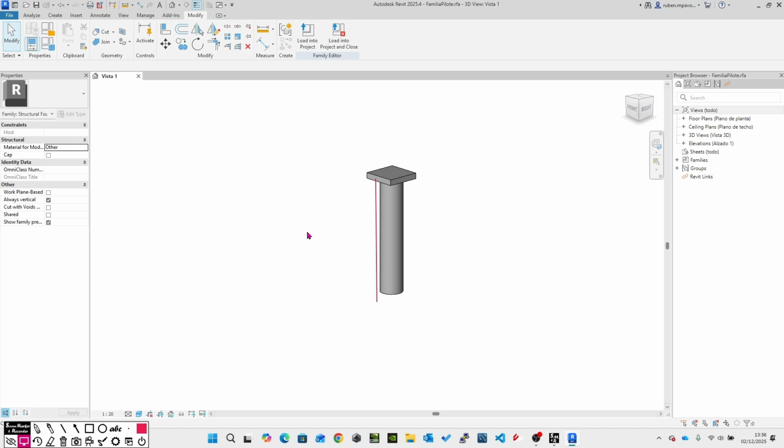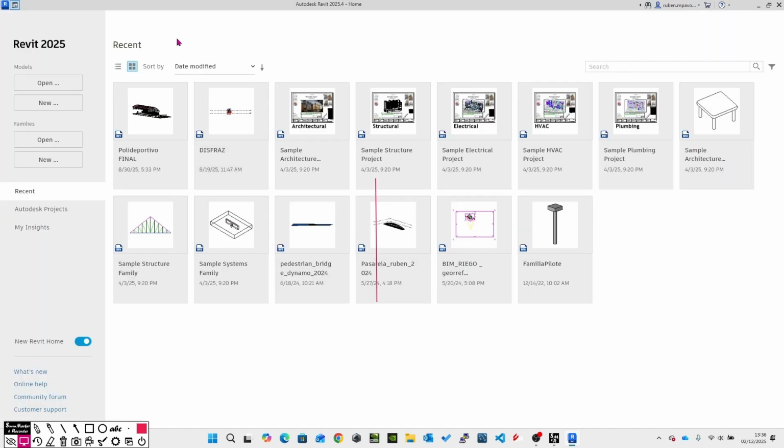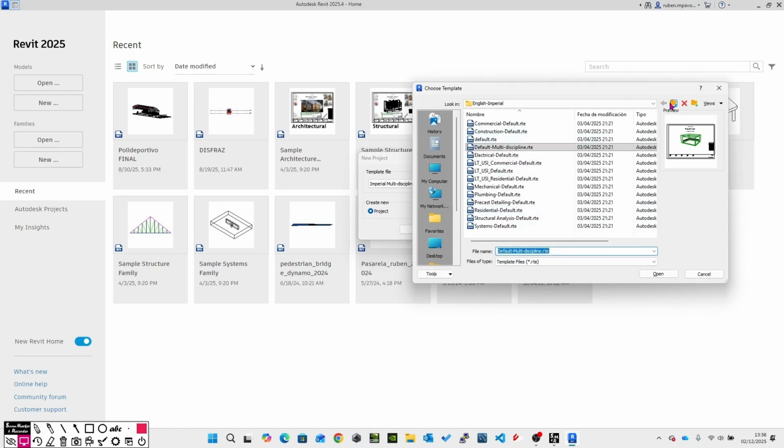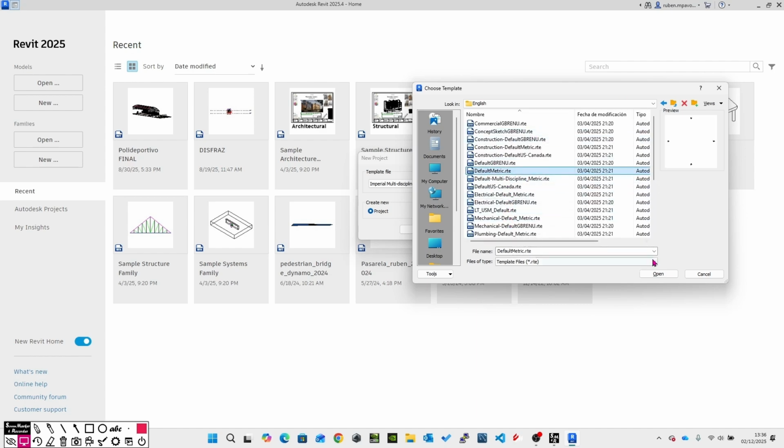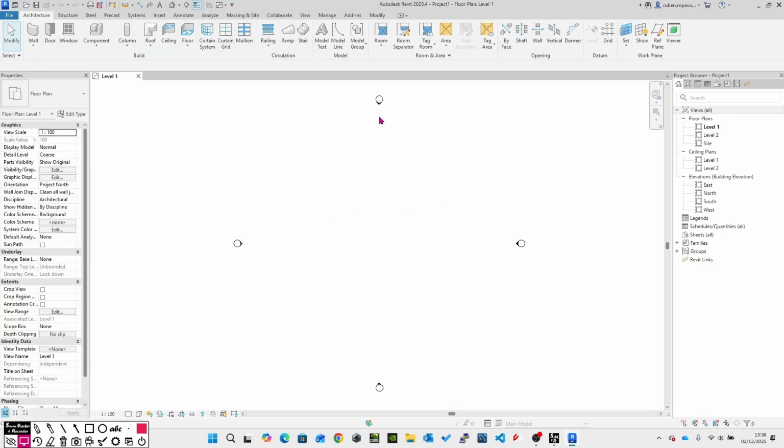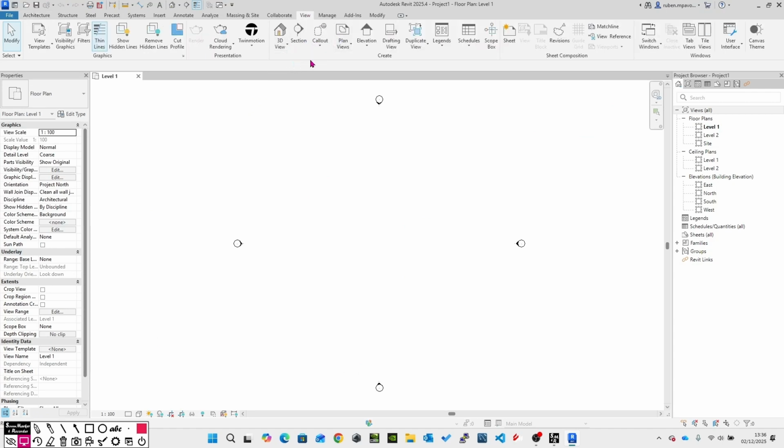The other important thing is that I can provide an easier way to manage the family inside a project. Remember that we are not in a project, we are now in a family. So I am going to close it because I have the family created, and I am going to open a new project. As we have done in the previous video, I am going to the English metric, English default metric, and open. I am going to create a 3D view, and go to this level 1.